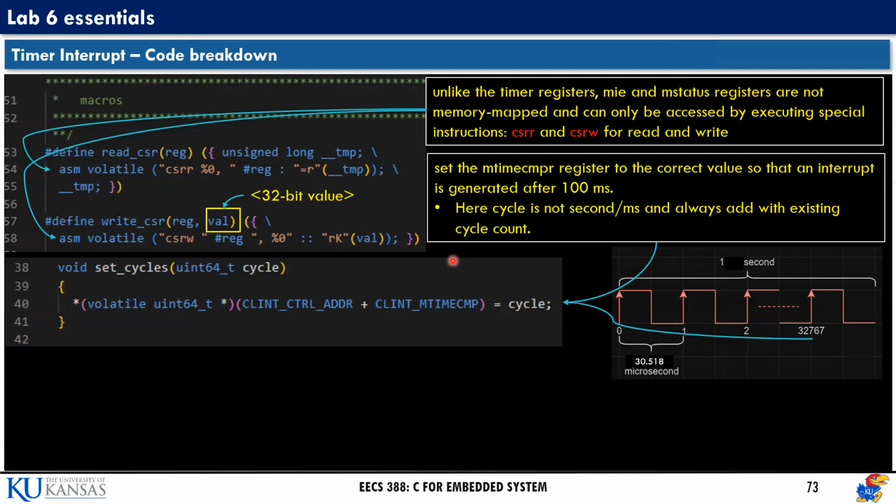If the 100 milliseconds have passed, our interrupt handler will pass an interrupt signal to the CPU to tell it: whatever you were doing, which was turning on the LED, please stop, and then wait 100 milliseconds, and then you can do whatever you were doing previously, right?